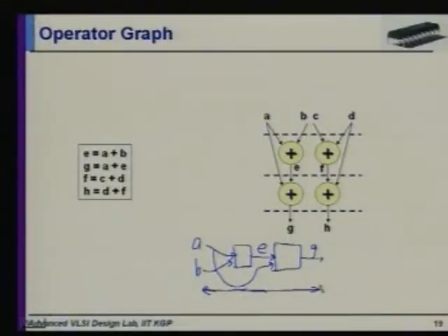So now look at the problem. You have a huge circuit, different parts of that circuit can work at different speeds. Your job is to find out what should be the clock speed so that the overall thing works the fastest, right? If you put in too much combinational logic between the clock pulses, then the clock width will grow and it is going to slow down other parts of the circuit.